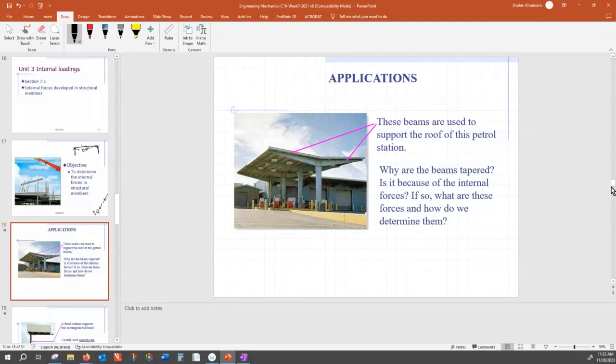My answer to this question: if that structure was made of jelly, if that was made of something soft, something like jelly, under the weight of the roof, this would have deformed like so. Change of radius of curvature, right? That's not difficult to visualize. This structure won't become longer or shorter. It changes the radius of curvature.